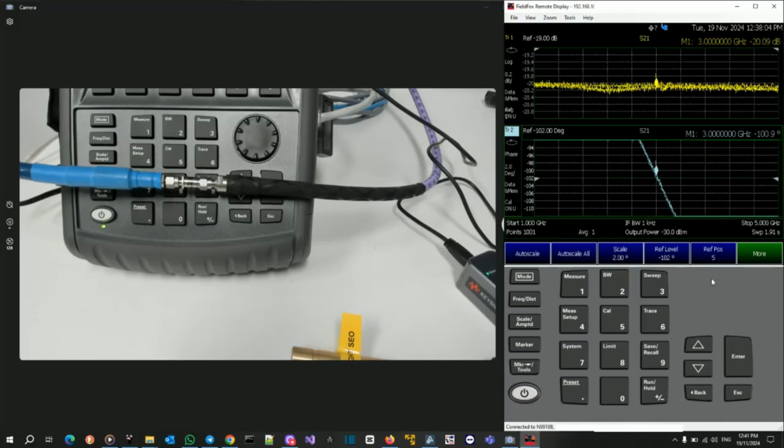As you can see, the calibrations for all three, the normalization, then full 2 ports with unknown through and also full 2 ports with known through calibrations, look quite identical. If you need something more accurate than that, you might want to really use the torque wrench to make it more accurate. Right, so the last thing I want to show you is the QSOLT.